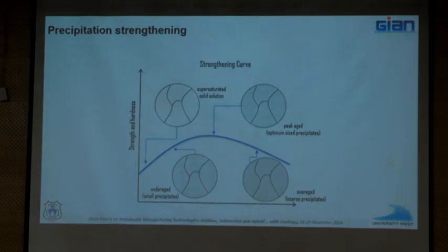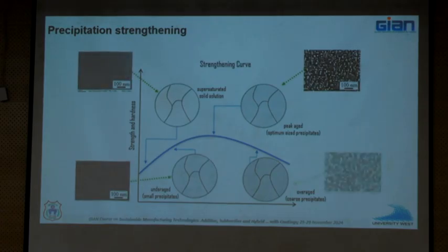You want to age it just right. So you want to perform what is called peak aging, to get the right kind of mechanical properties. You don't want to underage, you don't want to overage, because on either side of peak aging you begin to compromise the mechanical properties. And that's the reason we wanted to investigate this at various instances.